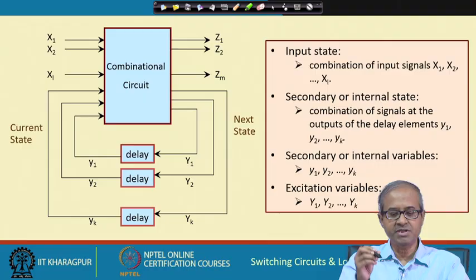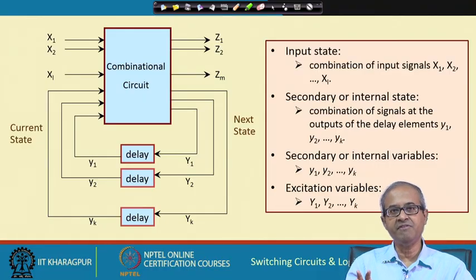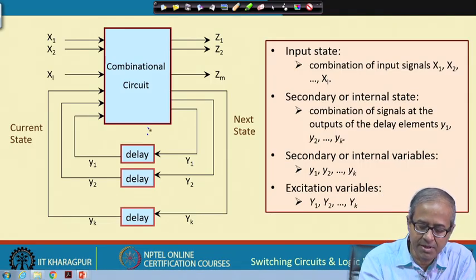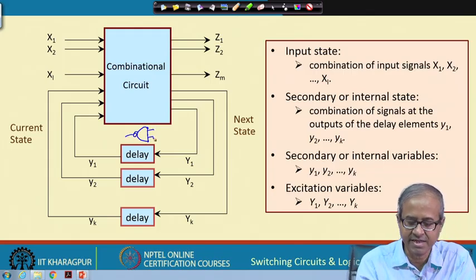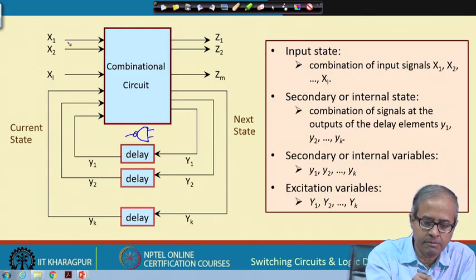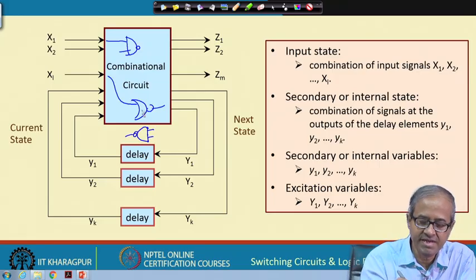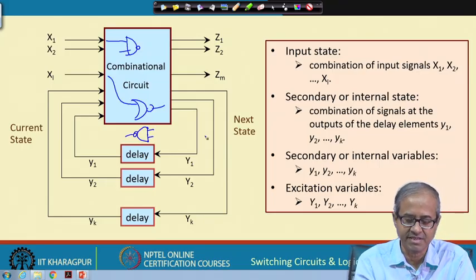But for an asynchronous circuit, because we do not have any separate flip flops, everything is determined by the gates. The delay that we are talking about here can be just a NAND gate, a gate. These inputs are coming, and the inputs are also going into some gate. So, there are such delay elements everywhere in the circuit.